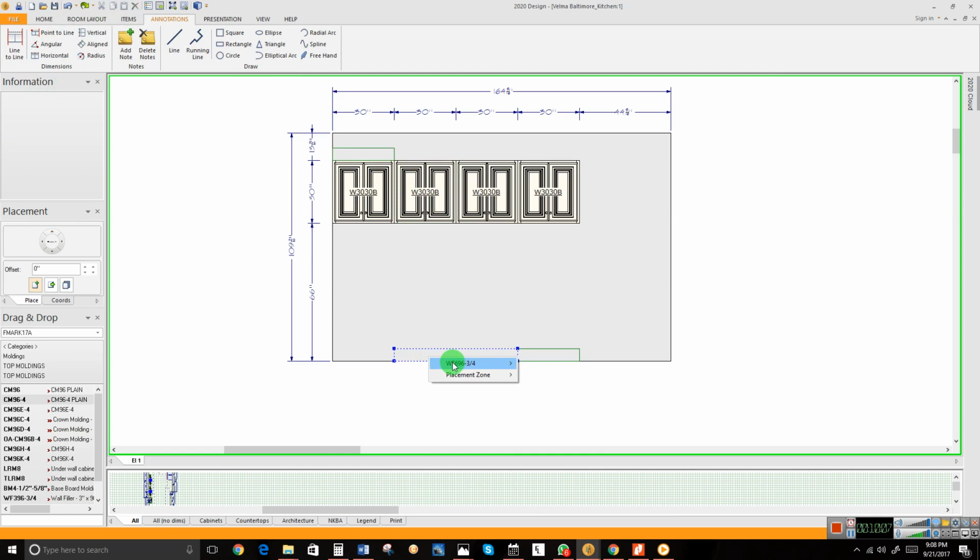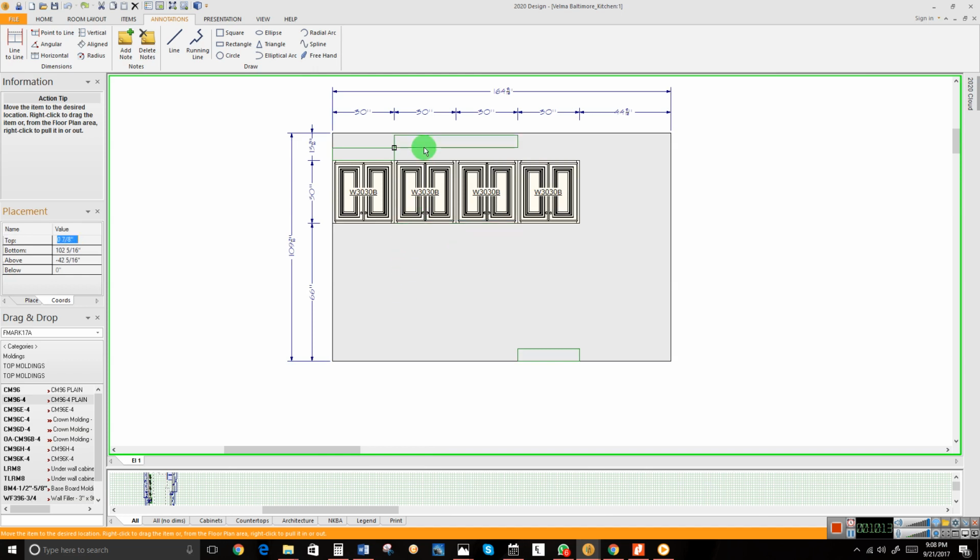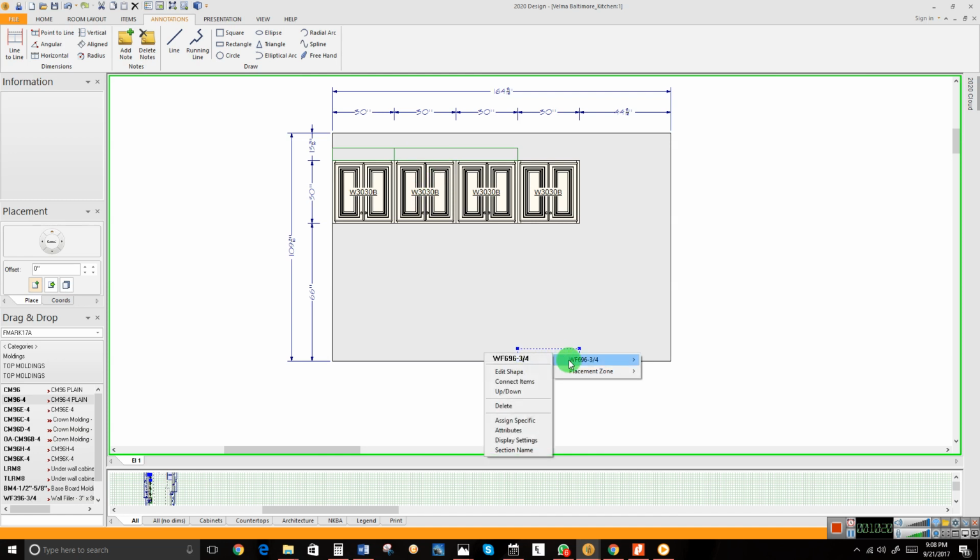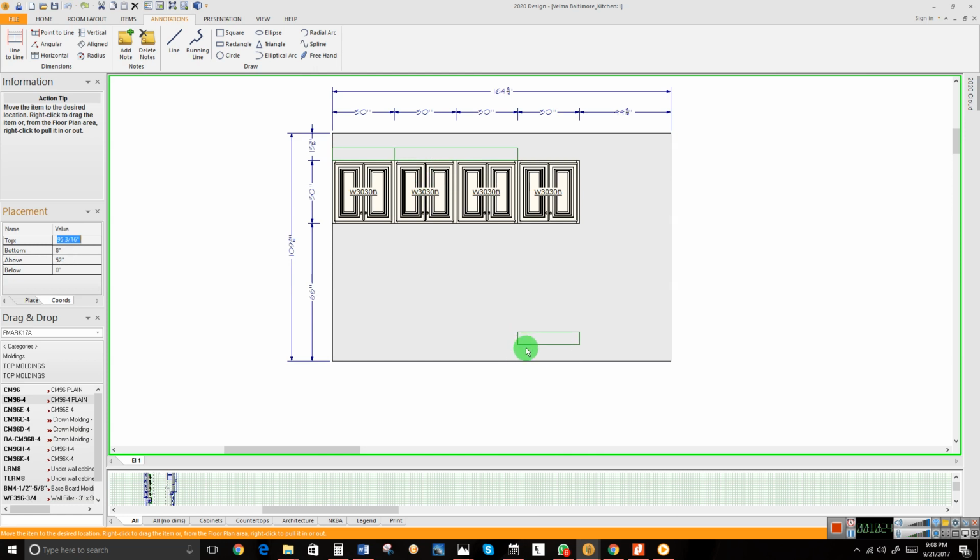Right click, okay, and then you see the up and down arrow, which is the best. So you take it up and you snap there. All right, then the last one is this one, which is also the up and down arrow. You take it up. Now, if you don't know the height you want to take it to, supposing there's no reference point where you want to snap, how do you decide the height?